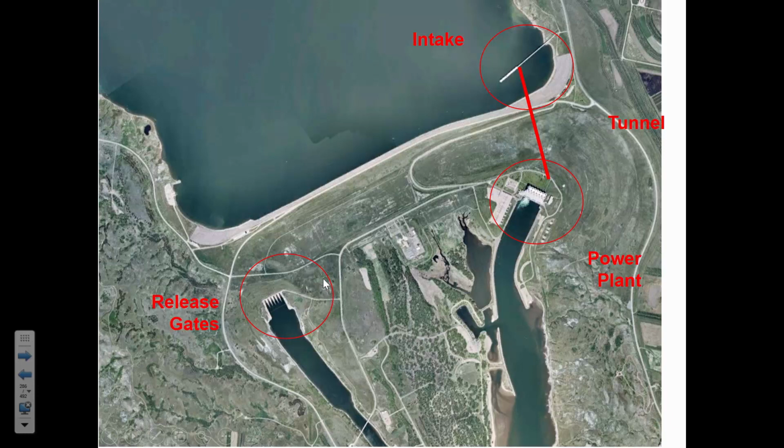And then, not pictured here, dams would also have an emergency spillway in case the water gets high enough that it's just going to go over the face of the dam. There's usually a certain place where they've ruggedized and intentionally improved the surface of where the water would flow and spill over the surface of the dam to try and prevent scour.